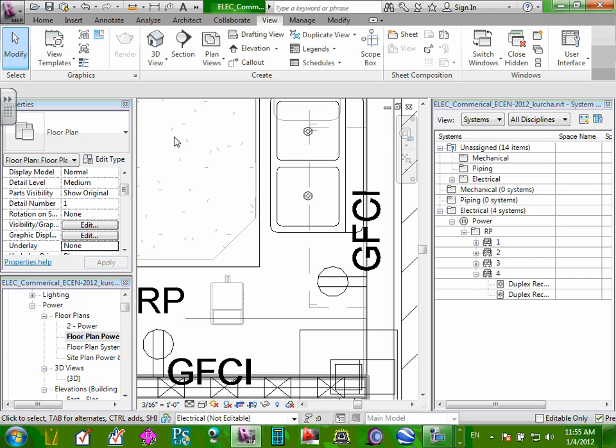And by the way, we're picking receptacles. If it was an air handling unit in the corner, same way. Pick the air handling unit, power, and add. If it's one receptacle, you pick it up, you power it, and if you want to add another load to it, you just edit circuit, add to circuit, pick that thing and hit finish. Make sure you hit finish when you're done. Cool? Let's do one more circuit, guys.